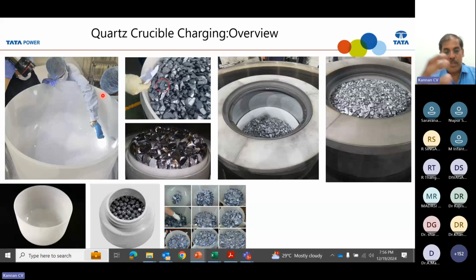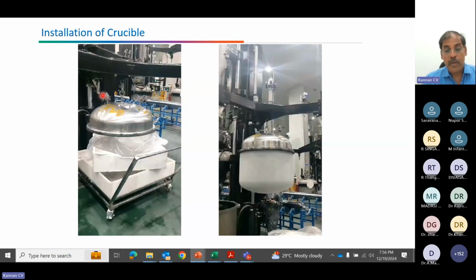But still, by putting this kind of protection layer, you can minimize the amount of oxygen coming into the melt, so that the overall oxygen concentration in the crystal, and in the wafers you slice from it, will be lower. And if you use gallium instead of boron, you are removing boron 100% and reducing oxygen concentration too. So overall, the minority carrier lifetime will be enhanced by doing this.